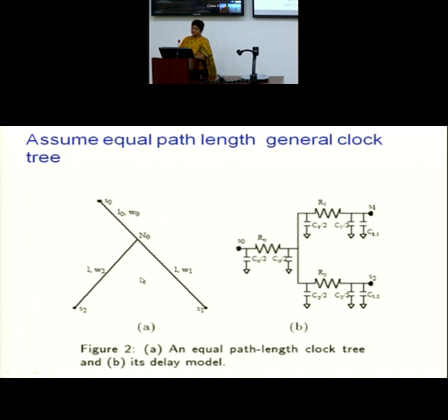First of all, I need to determine the locations at which I should be inserting the buffers. So I will be determining the buffer insertion points, or BIPs. It's very simple. Normally we go by the equal path length approach, and then we go on increasing the number of buffer insertion points. When I insert my first buffer insertion point, it would be nearly half. So the total path length from here to here, you make it a half, so it comes somewhere here. Similarly from here to here, so this would be my first iso radius. So I would be inserting a buffer here and a buffer here.